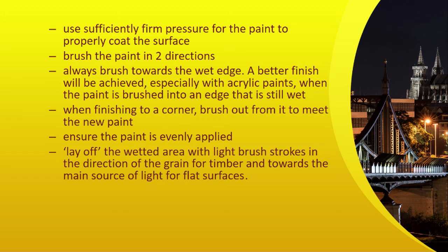Ensure the paint is evenly applied. Lay off the wetted area. Laying off is applying the finish strokes with light brush strokes in the direction of the grain for timber and towards the main source of light for flat surfaces.